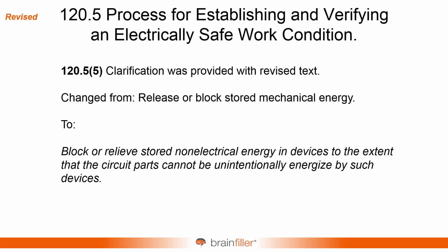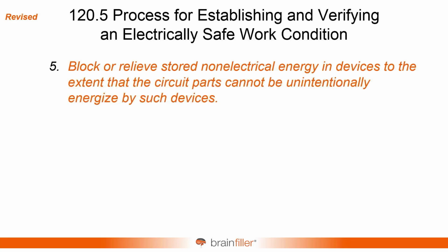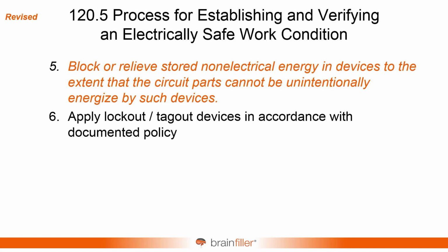So the new language is block or relieve stored non-electrical energy in devices to the extent that the circuit parts cannot be unintentionally energized by such devices. And that was added to the process of establishing and verifying an electrically safe work condition. Apply lockout tagout devices in accordance with documented policy, and that documented policy must be in compliance with Article 120.